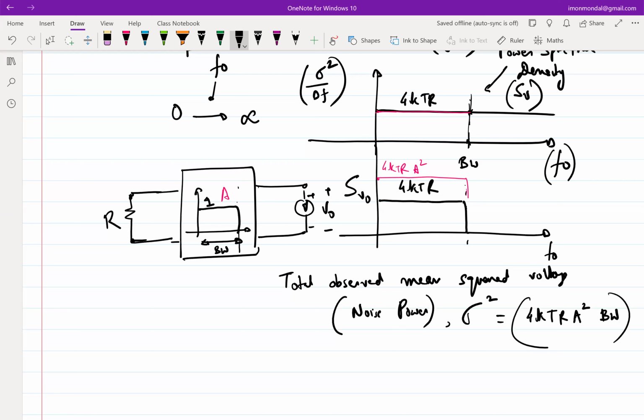The reason, so essentially, now the question boils down to characterizing your design. Let's say you have designed something, you have designed a receiver, right? Then you have to characterize it in a certain way to figure out whether your receiver is noise resistant or not. So how will you characterize your receiver? One way to characterize the receiver is to say that, obviously, I'll apply a tone, that is a sinusoidal frequency, anywhere within the bandwidth, and I'm going to observe the strength that is received and so on. And I'm also going to observe what is the noise that I receive, right?